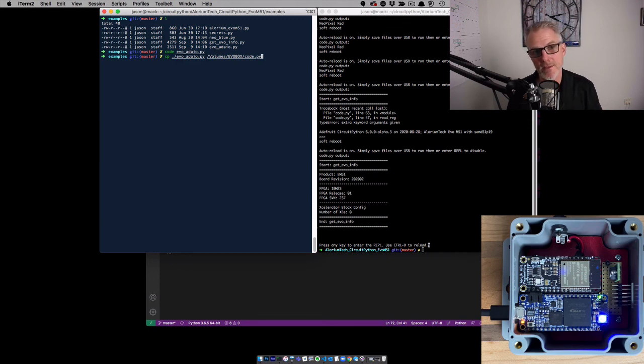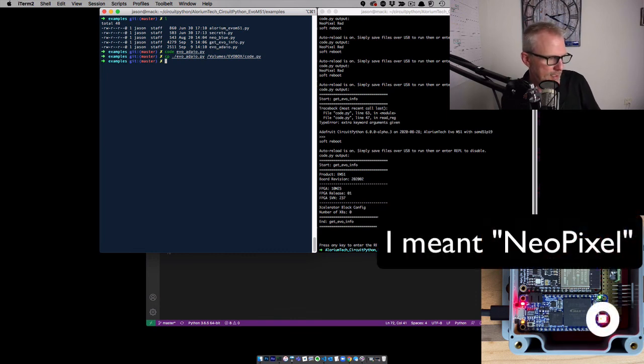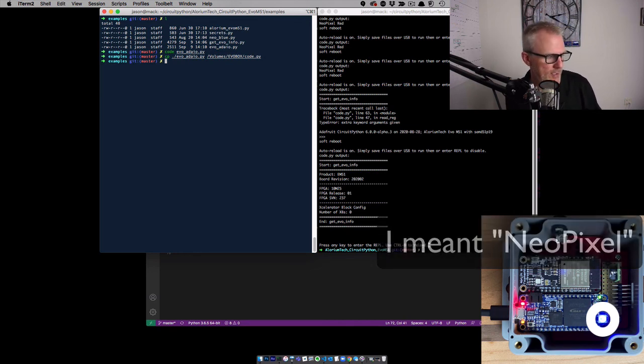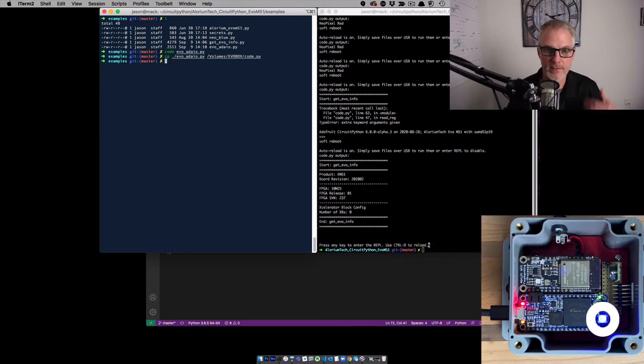It defaults to CircuitPy when you mount your CircuitPython drive, but it doesn't have to be that way. So if we copy that over, we should see it update. Now, that red LED tells me that it has changed because I know that's a status LED for this program. And when it's trying to get connected to the internet, it'll be red, then it'll turn blue, and then it will connect and start sending data.